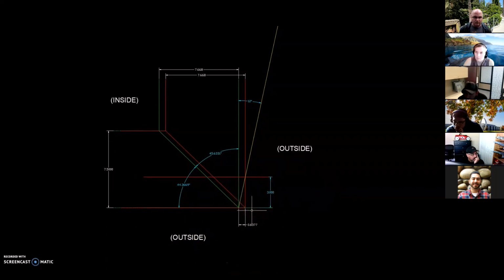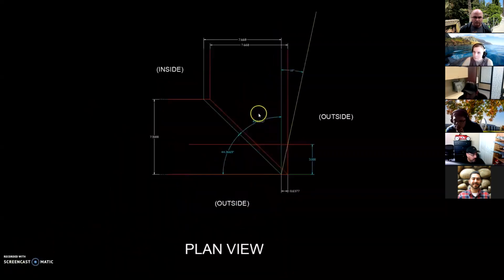The green point on the bottom footprint, and 3 inches higher and a little bit to the right, the red point on the top footprint. And the moment you have that in front of you, you can make a line between the points, and that will be your tilt. To record that in a clear way, we're going to make a vertical section perpendicular to the miter lines.